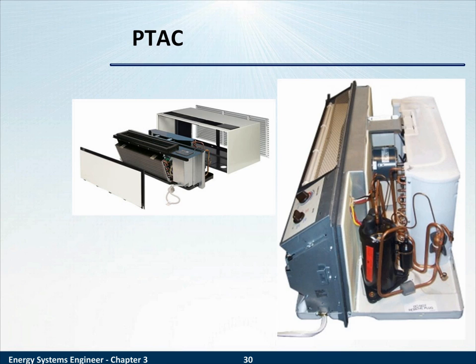Like a window air conditioning unit, however, they can be quite inefficient. For example, if you have, say, 1,000 rooms and you're at 85% occupancy year-round, this is not unheard of for some tourist places. It's probably cheaper to install boilers, chillers, hot, cold water. However, if your hotel is 75% occupied Monday and Friday, 50% Tuesday, Wednesday, Thursday, 20% on Saturday and Sunday, then a PTAC is probably a better solution for you.